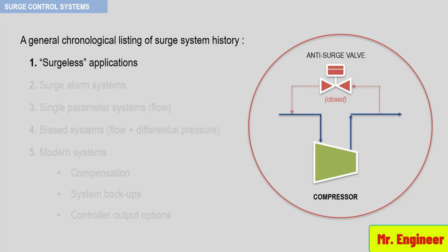However, if any of these facts can occur, the compressor in question can be forced into surge as a result of the inability of the compressor to produce the energy required for the throughput flow. Recall that the operating point of any compressor is the equilibrium between required process system energy and the compressor-produced energy. Keep in mind that both of them can change and will certainly do.